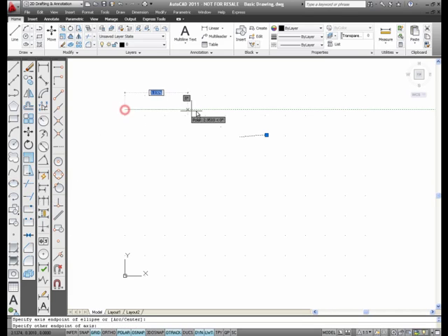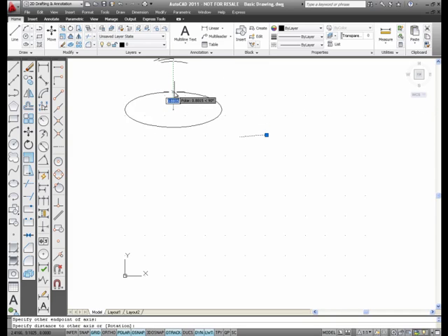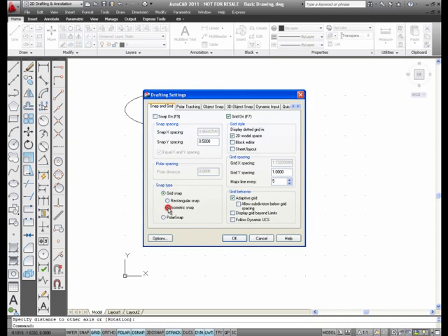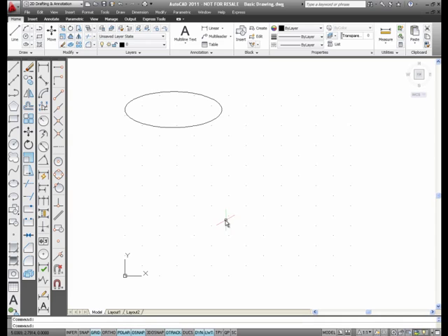All right, so the ones that I want you to remember are approximate ellipse. This is the approximate ellipse. Remember, maximum diameter half of the minimum diameter. To get to isometrics, you need to go down here to snap or grid, right click, pick settings, change to isometric snap, pick OK, look at the crosshairs, select ellipse again, don't forget, type in I for isocircle, press enter,